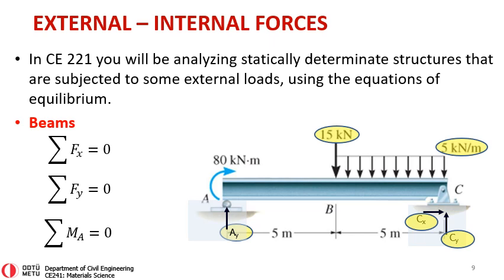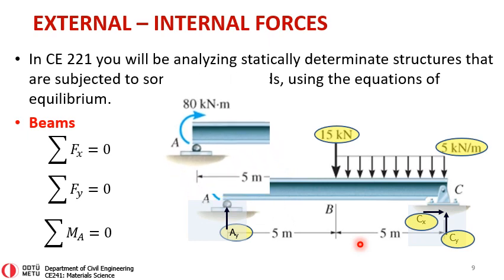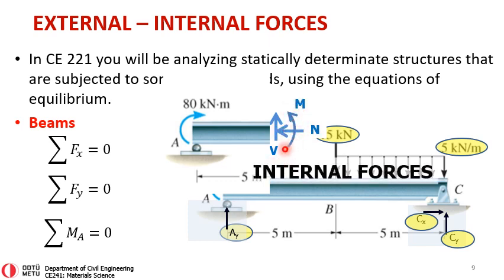Well, you cannot see the internal forces unless you cut through that beam. And if you were to cut through that beam, you will see that to bring this body to equilibrium, because it's a statically determined structure, you should be able to put some forces over here. And that could be a shear force, a normal force, or a moment. And these are now called the internal forces that are developed within that beam.